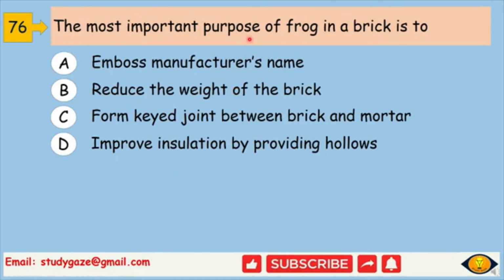76. The most important purpose of frog in a brick is to emboss manufacturer's name, reduce the weight of the brick, form keyed joint between brick and mortar, improve insulation by providing holes. Answer is C. Form keyed joint between brick and mortar.